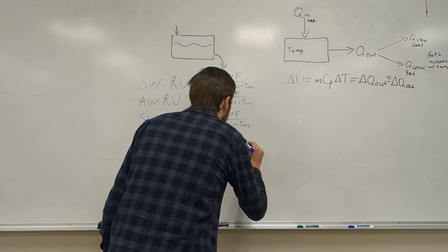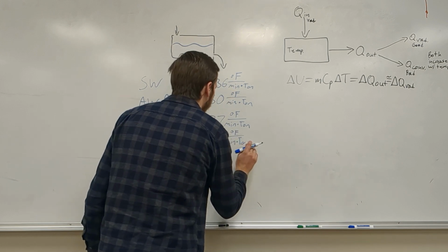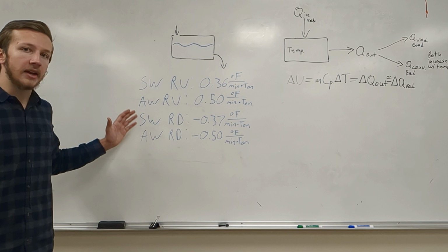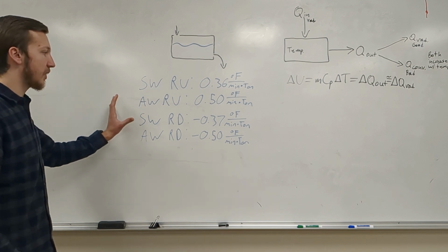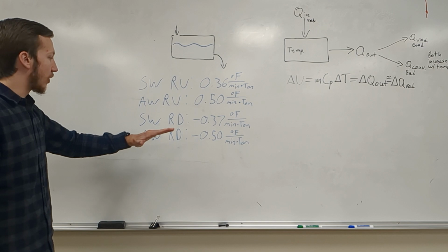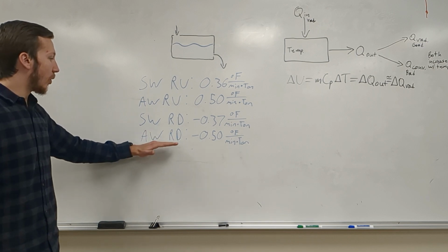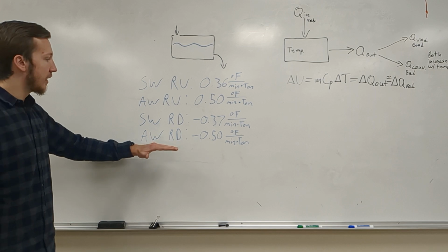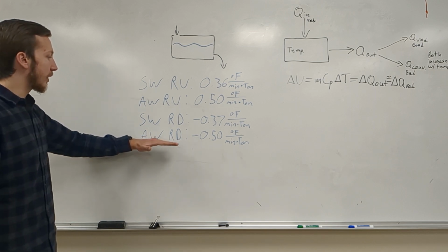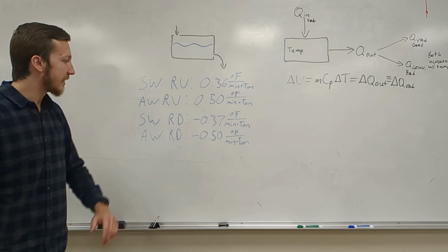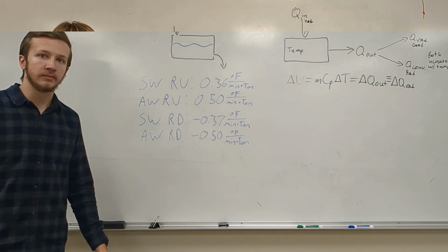So the exact same almost as the ramp up. So once again, considering our view factors, this is also not very surprising, as once the lights are turned off, the angled wall surfaces have a greater view factor of the sky, and therefore have a greater chance of radiating heat to space. So we can see that reflected in this slope.